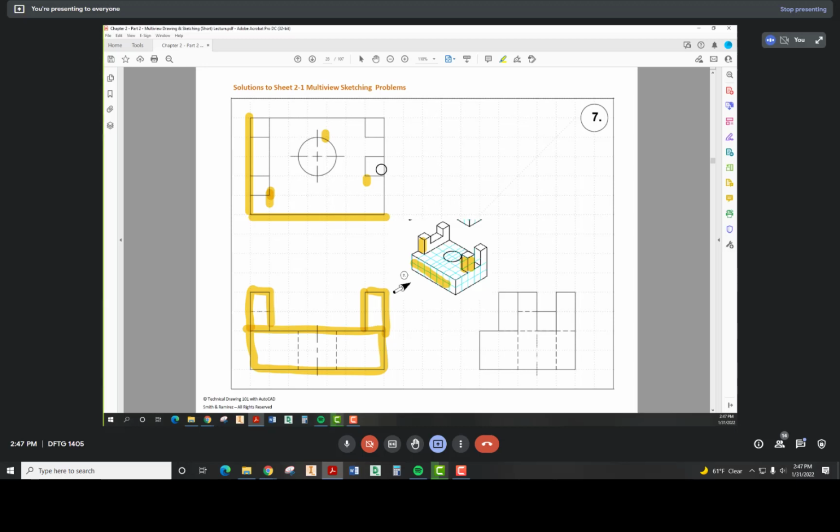So now we've got something else here, that we've got our location of where these start and how wide these are. Right now this looks like one solid thing, and we can't put a hidden line down here to show that it's broken into 2 pieces because there's a visible line there. So we've got these 2 castle blocks. Then this castle block is 4 units deep, but you know, we've got a little step here. So the only thing that we can't see here is how deep is that step. We've got to have this view for the depth of this step right here.